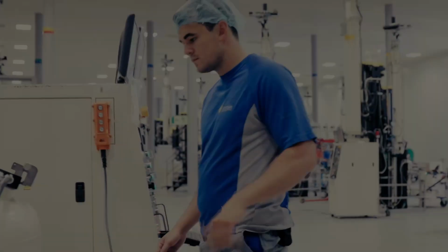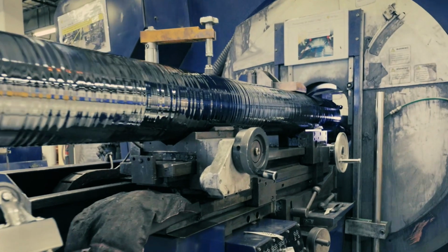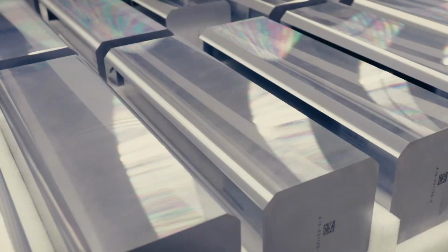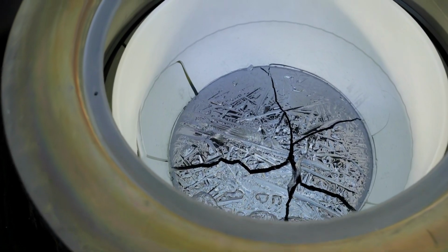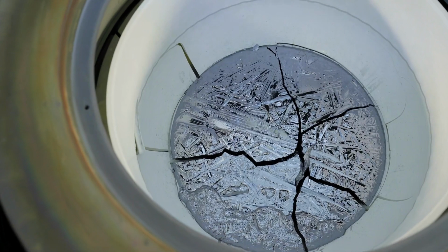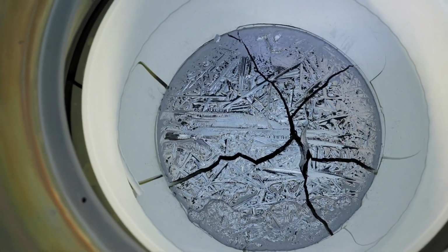Materials' properties, such as purity, impact their ability to be reused. An inventory of the waste properties has been performed for three important material flows: silicon kerf from sawing of wafers, silica from crucibles used in crystal pulling, and graphite from crystal growth furnaces. We will focus here on silicon.